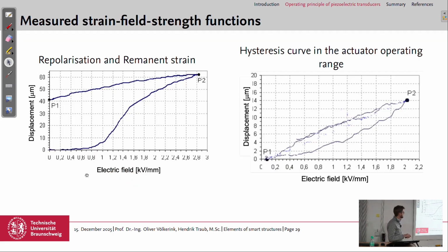So if you have 0.5 millimeter thick material, you would need only 1.4 kilovolts. And if you have material which is 2 millimeters in thickness, you would need 5.6 kilovolts. Yeah, the distance between the electrodes.